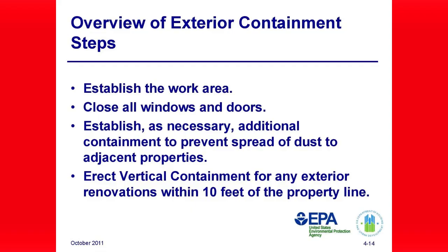If you're going to use any kind of paint stripper, make sure that you use a minimum of 2 layers of sheathing so you can remove the top layer once you're done using the stripper, and the bottom layer can always remain until the work has been completed. Number 6, ensure that the dust and debris do not contaminate or migrate to adjacent areas and properties. Whenever waste or debris is collected, remove it from the work site and clean up a minimum of once a day.